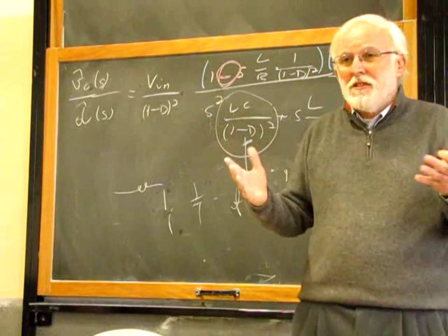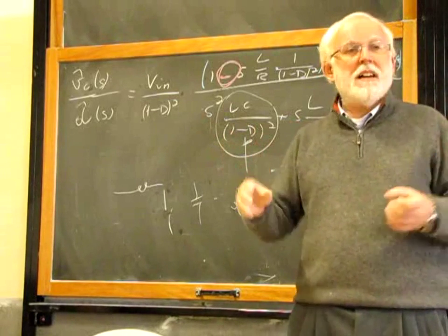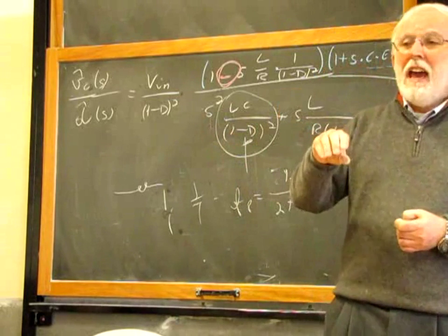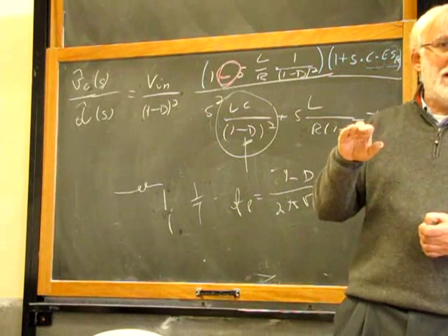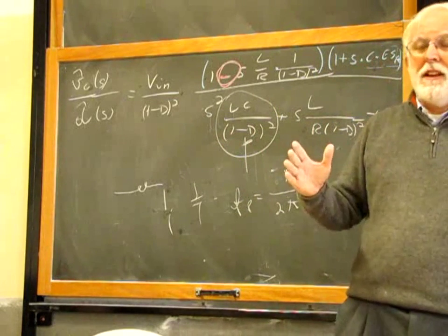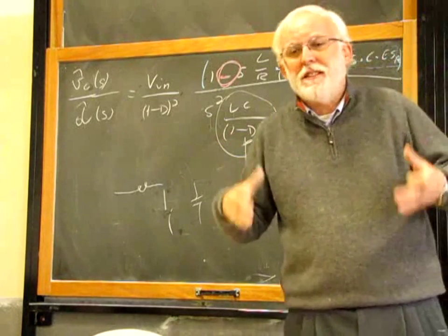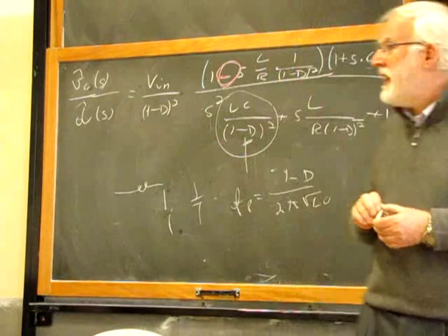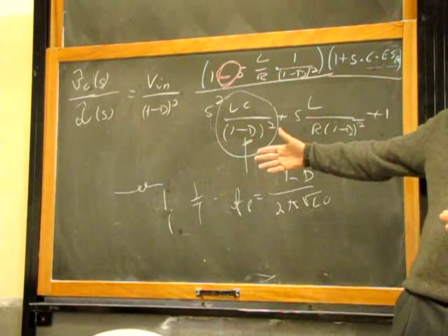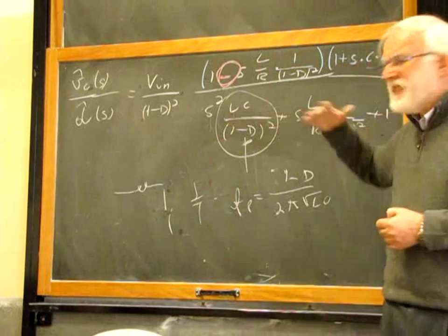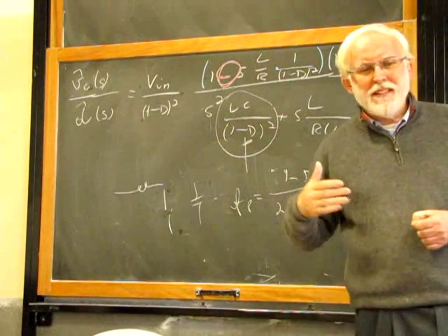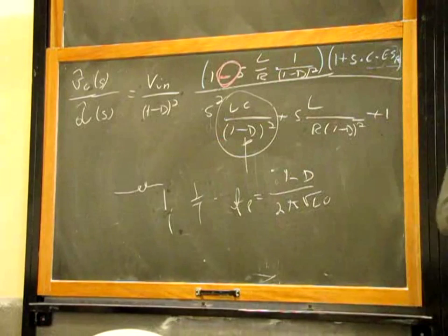That's okay, but it's not a smart way. The smarter way is just to find a bias point and, for each nonlinear component, substitute its linear model. Do not solve the nonlinear equation for all your circuits. That is a lot of pain in the neck. That is exactly what we did in this moment. But this was the first result they got. And it's still a very systematic way to solve it. In some cases, it's the only way you have.